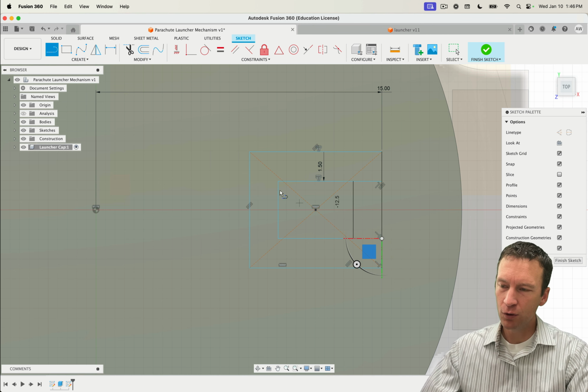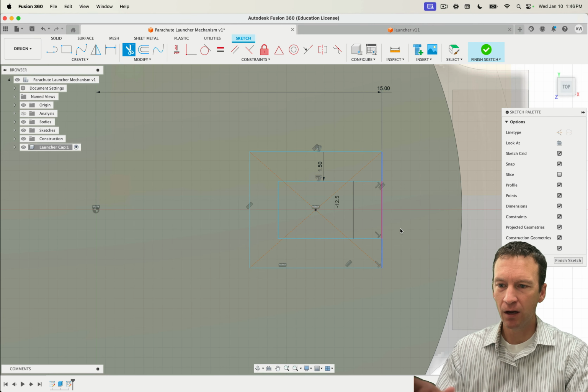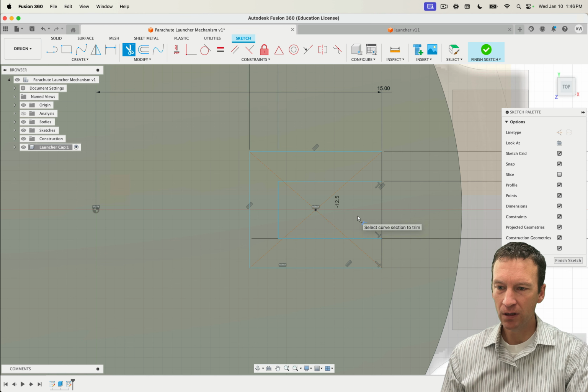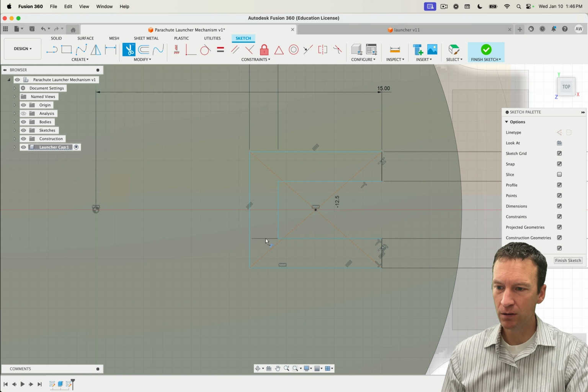And now I'm going to use a new tool that's called the scissors tool or the trim tool. So if I grab the trim tool, I can cut away all of the extra lines that I don't need. And in my case, because I just really want this to be this outer portion, I don't really need that guy at this point. That looks pretty fine. I really don't even need that guy. And that's all my other geometries in place. So we're good to go.